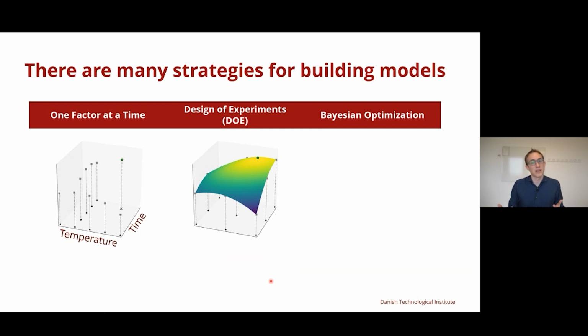Now, that's all well and good, but one of the challenges of using DOE in an industrial context is that the number of experiments you need to run before you can draw the map becomes really big the more factors you have in your system. And typically for optimizing processes or products, you would not really want to do a DOE for more than, say, 4 or 5 factors at a time. So 4 or 5 things we change. Otherwise, the number of experiments becomes big very quickly.